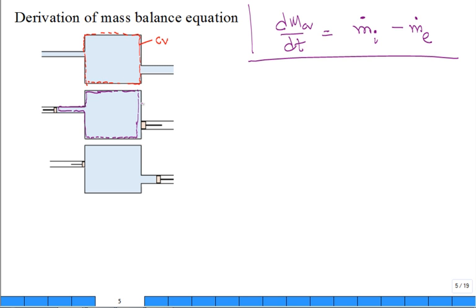So that's a control mass which is starting at time t, and the flow is coming in here and going out this other side, and at a later time t plus delta t, you pick the time such that all of the fluid which was about ready to enter right here does enter, and then the boundary of the control mass is flush on this surface right here.